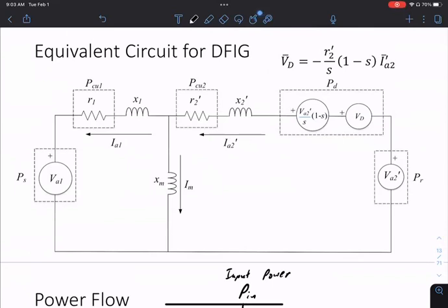So I'm going to add these two and call this the total power coming in. Total power coming in is not necessarily bigger than the developed power. It could very well be that this term, by setting the phase, turns out to be a negative active power. So the grid is giving you negative power, which means you still have some power flow out of this side. P in is easier to collect and think of a loss going this way, because all the loss mechanism happens in this one and this one here. Any other questions?